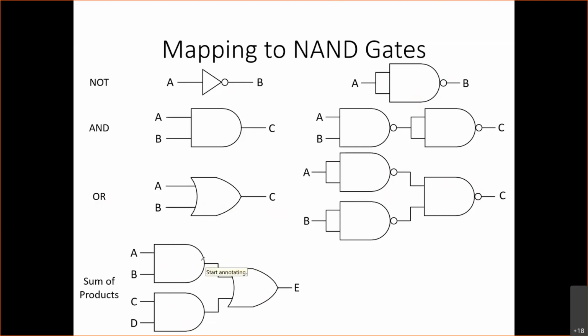So here, if I invert the output at this NAND gate, and if I invert the output at this AND gate, and then if I invert the input at this OR gate, and I also invert the input at this OR gate, have I changed anything in the circuit? I haven't changed anything, right? I take the signal, I invert it, and then I invert it again. Same thing here. I take the signal, I invert it, and then I invert it again. Okay? Is that clear to everyone?